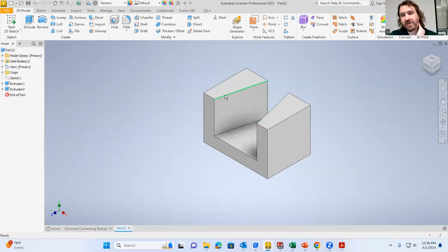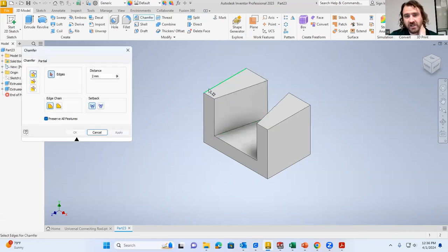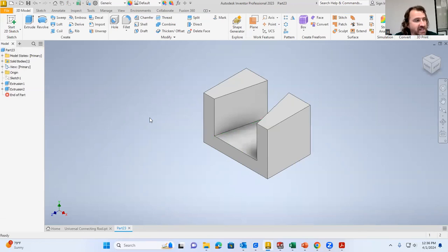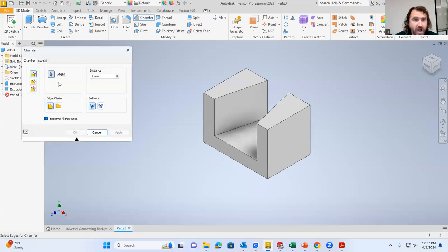Now the last step here is I need to chamfer. I need to cut off this surface here and this surface here. I need to trim out both of those. But the distance I need to trim them out is actually two different distances, because from this edge to this edge is what's getting cut, and that's only 30 millimeters. And it's cut from this edge all the way back to this edge, which is 40 millimeters. So when I set up my chamfer, I want to make sure I go to two distances and then set my distance 1, this one here, which is going back horizontally. This is 40.